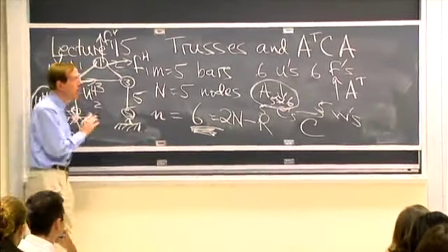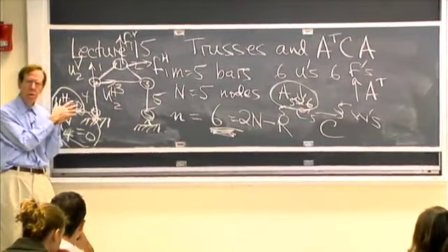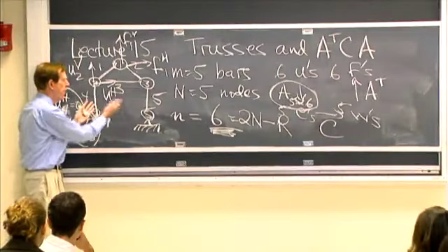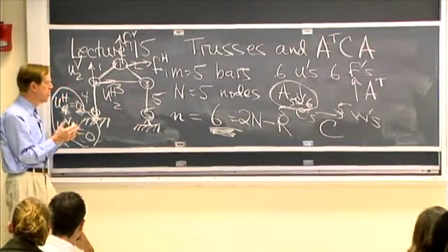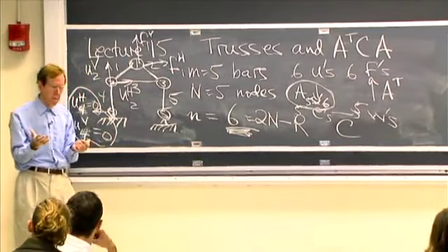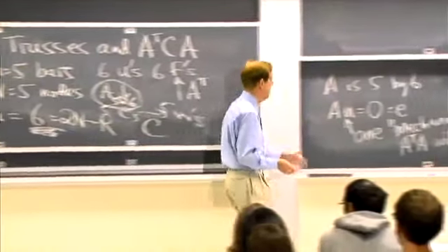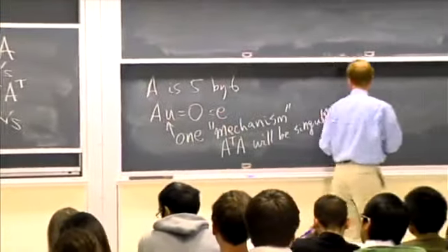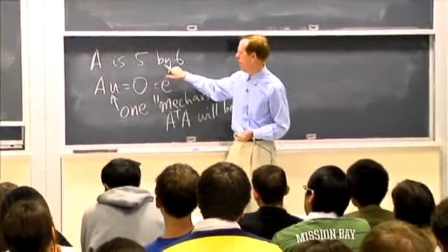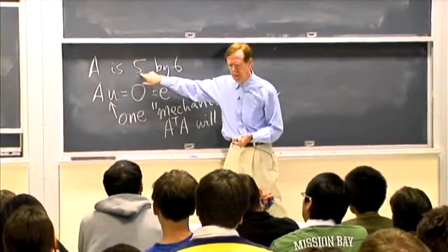And I believe that if you look at this truss, you could tell me, and you could draw a movement of that truss in which there is displacement, but no stretching. Let me ask you how to draw that. And I believe everybody understood why there was a solution. It was because we have 6 unknowns, and we only have 5 equations.